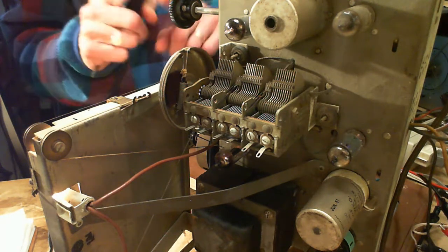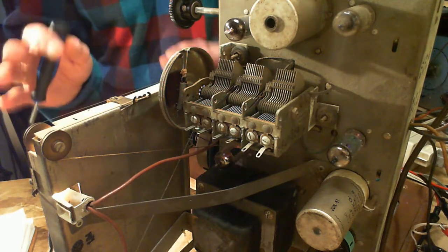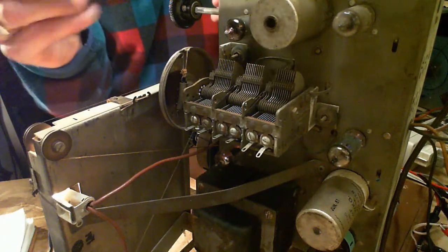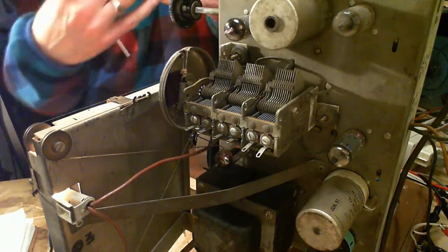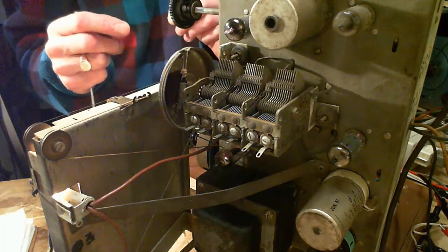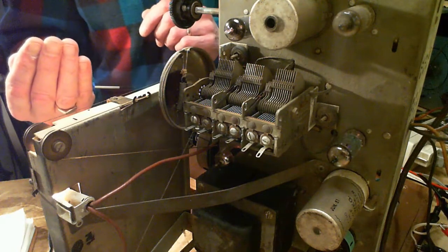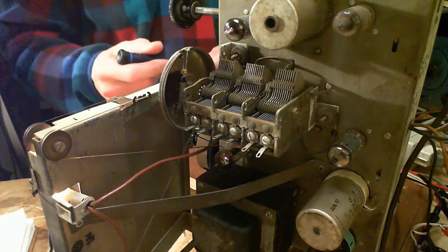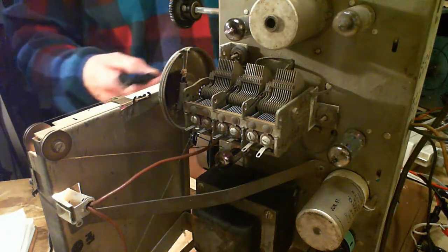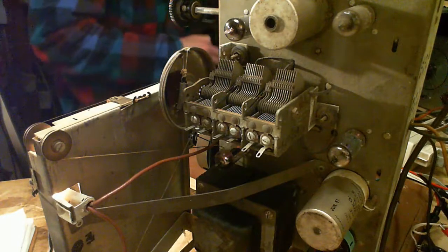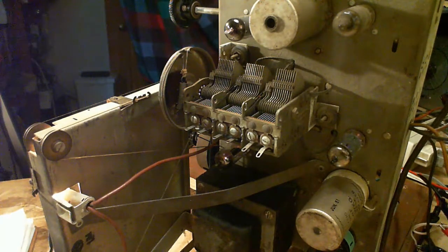If you're doing a broadband, and a broadcast band is a broadband because it almost doubles itself, use these big capacitors to vary a lot of capacitance. But maybe on the band spread bands, you only want to vary a little bit of capacitance. So rather than move a big one a little bit, you take a small one and you move it a lot. So that means, if that's true, then the rest of these are going to be all in those small capacitors. Okay, that all kind of adds up a bit.